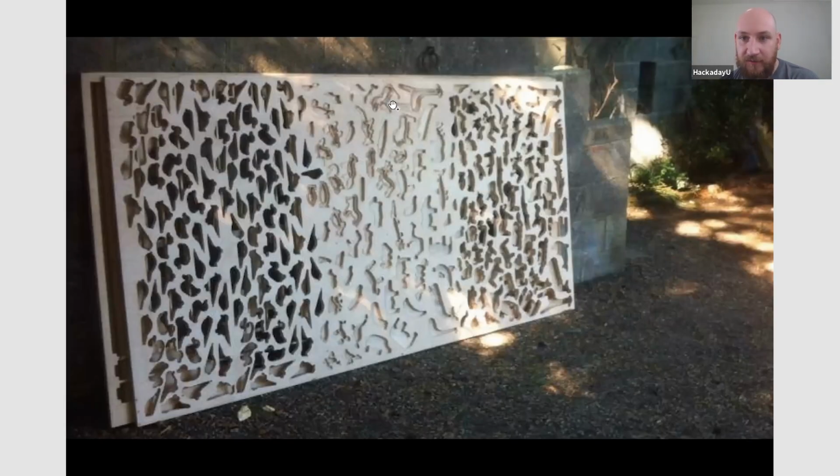And then these shapes are obviously rotated because I allowed them to be free rather than fixed in the nesting settings. And I set a rather wide distance item to item, and a distance on the edge, so that I can hold down screws on the edge. And there's an example of the carcass left behind.